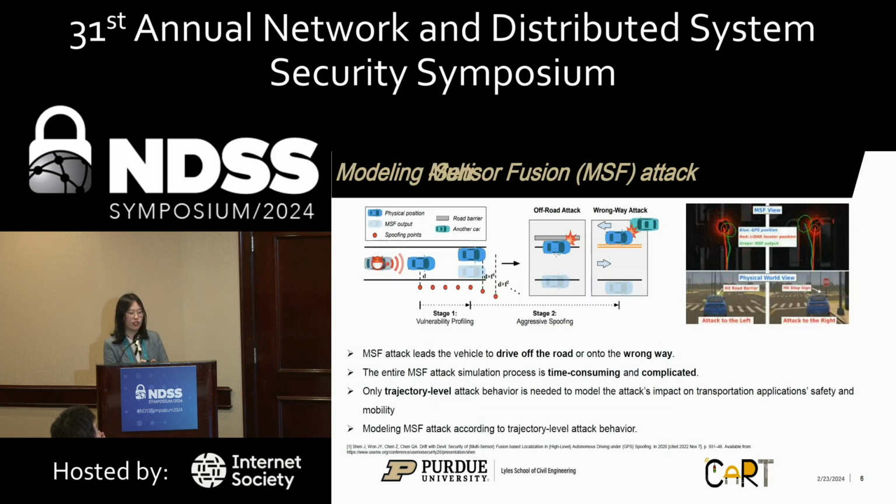The second model is the multi-sensor fusion attack. The MSF attack will lead the vehicle to drive off the road or onto the runway, and the entire MSF attack process is very time-consuming and complicated. If we want to model the attack's impact on transportation applications, safety, and mobility, we only need the trajectory level attack behavior. So in this work, we are modeling the MSF attack according to the trajectory level attack behavior.